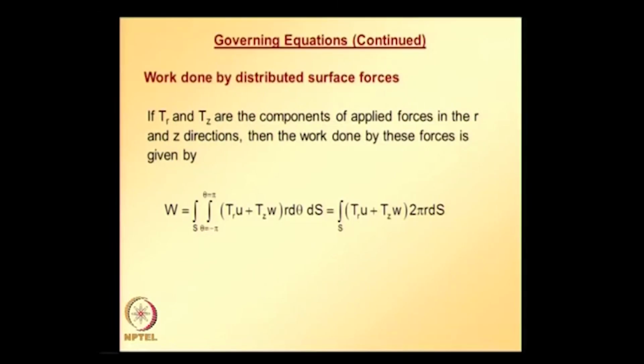Here we are integrating from theta minus pi to pi, because this is an axisymmetric problem, and by doing this we can eliminate theta in the expression for work done by the distributed forces. So, W finally is an integral over the line, or the side, along which the traction or distributed force is applied.